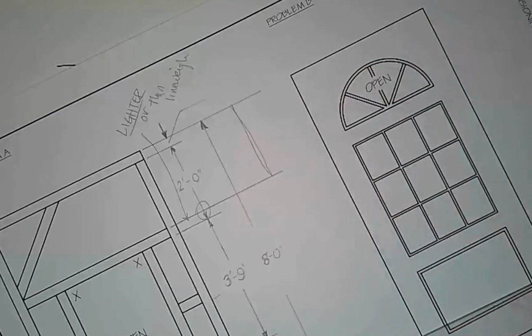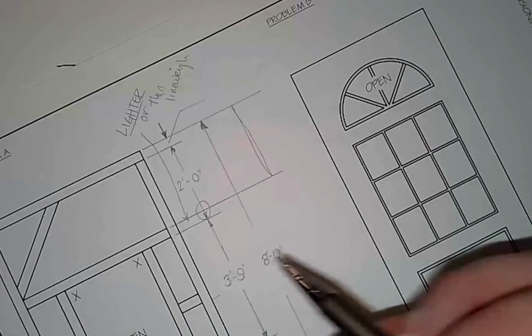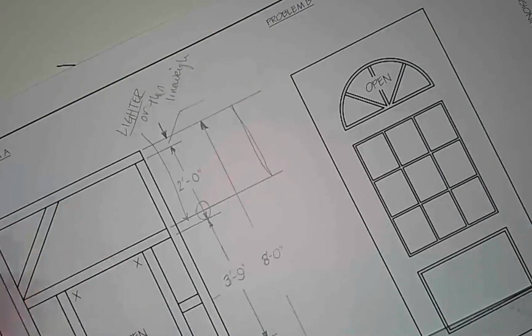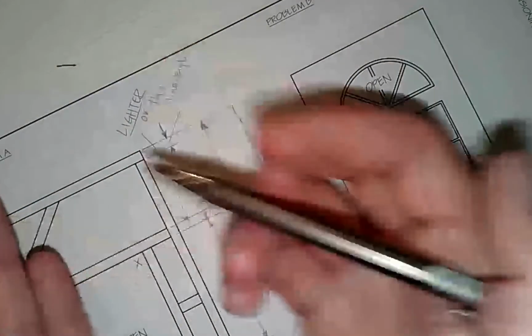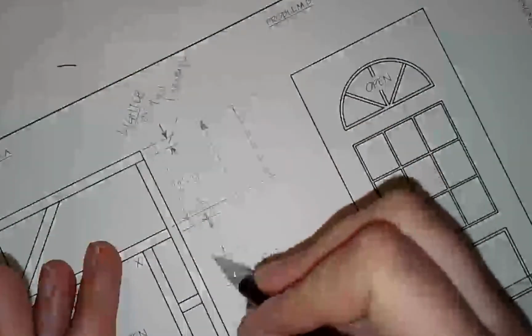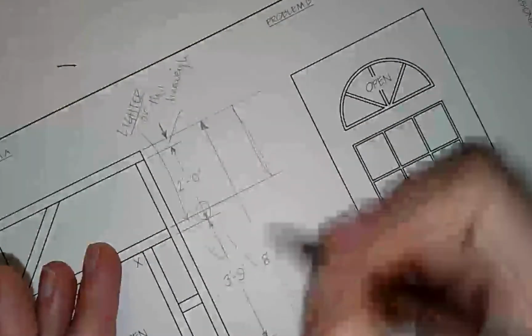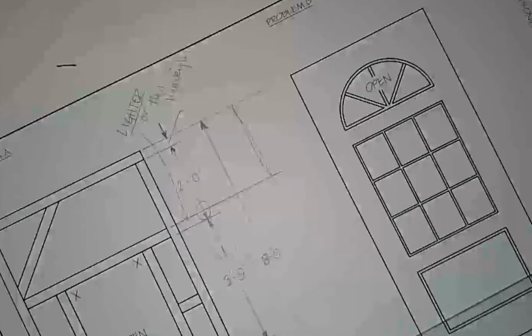So if you don't have enough space to do these side-by-side dimensions, you can also stagger them. So if they needed to be closer together, you could put this one up here and that one right there, and then they could be tighter to each other, right? Because you still wouldn't have to overlap your lettering on the space. So then we talked about arrows, great.